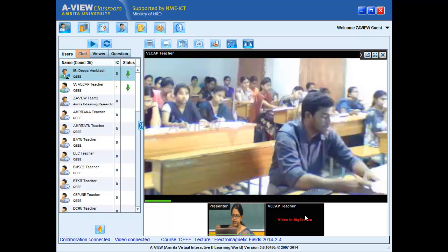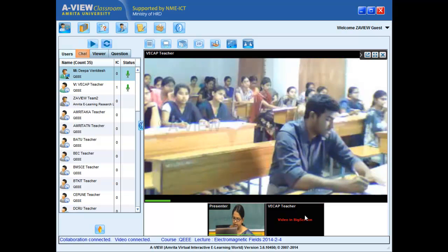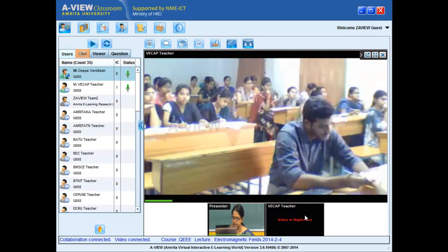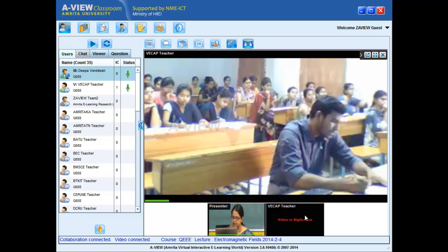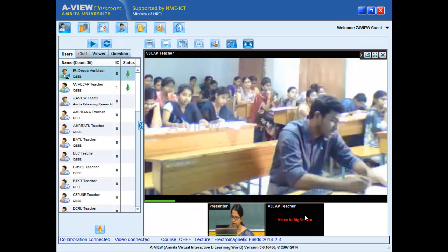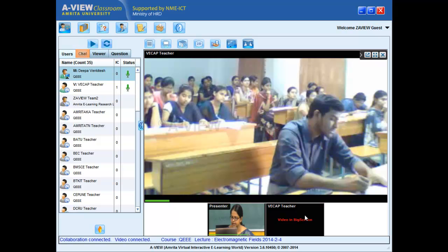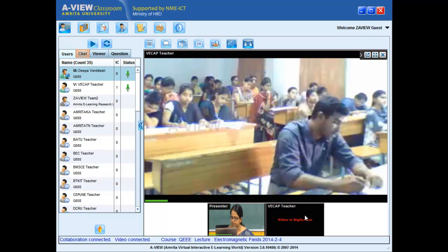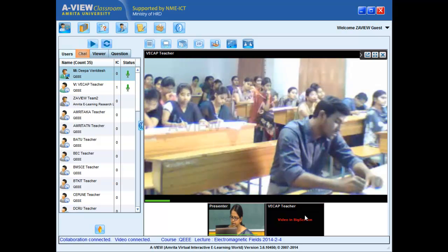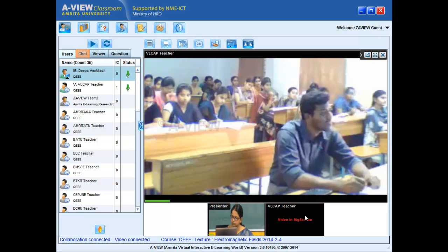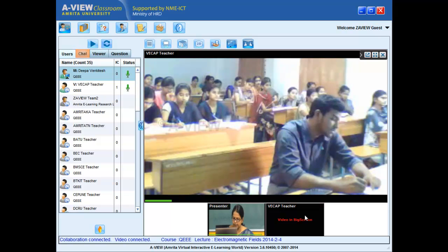So again, rearrange, I would get something like minus [I(z plus delta z, t) minus I(z,t)], divide throughout by delta Z, the same process that we did, is equal to C del V by del t at (z plus delta z, t) plus G V(z plus delta z, t). Now again, go back and apply the same limit.